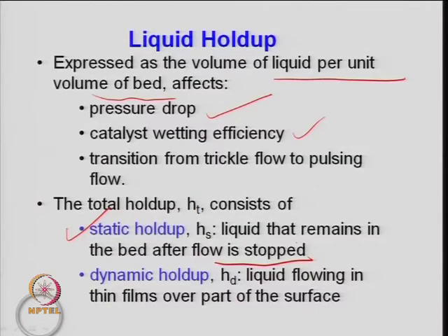And the same thing here: dynamic liquid hold up is the liquid which is flowing in the form of a thin film, because when you stop the flow, all that liquid will fall down. It comes onto the surface of the solid, trickles, and then falls down. So, when the flow is stopped, nothing is coming. There will not be any liquid, only the liquid which is between the pockets, something like a CSTR type zone.